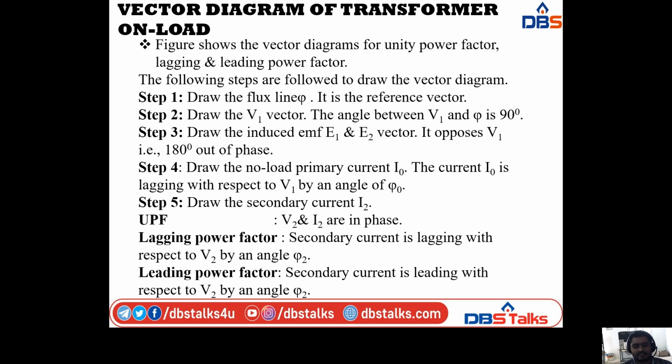Here I will draw the diagram for both the cases. This is the vector diagram of transformer on load. I will show three diagrams: for unity power factor, lagging power factor, and leading power factor. That means unity power factor for resistive load, lagging power factor for inductive load, and leading power factor for capacitive load.